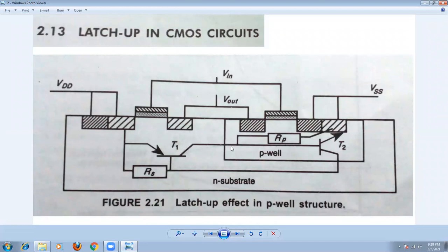Already discussed, there exists a latch-up mechanism. So again, just observe here. This is the substrate terminal. Depending upon the doping concentration, there exists a parasitic resistance component here. With higher doping concentration, the conductivity increases and the resistivity decreases. Compared to this material, this material has a moderate doping concentration, so the resistance of the substrate is high. Let us consider this the substrate resistance of the material.